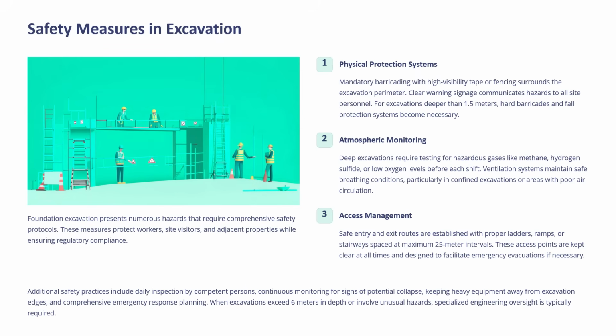Additional safety practices include daily inspection by competent persons, continuous monitoring for signs of potential collapse, keeping heavy equipment away from excavation edges, and comprehensive emergency response planning. When excavation exceeds 6 meters in depth or involves unusual hazards, special engineering oversight is typically required.